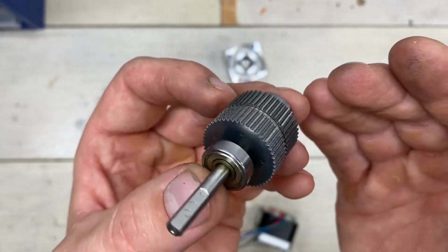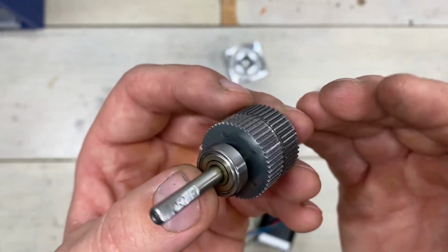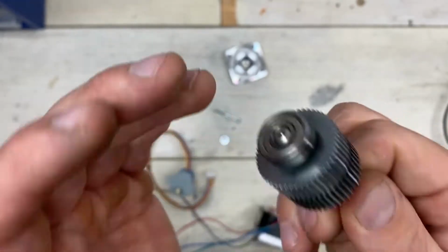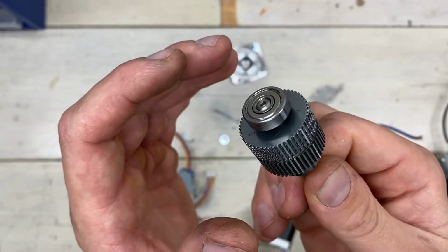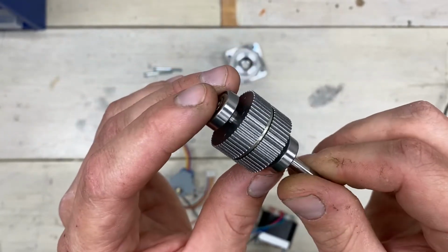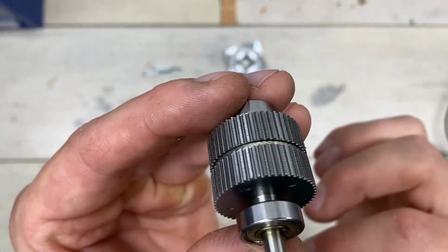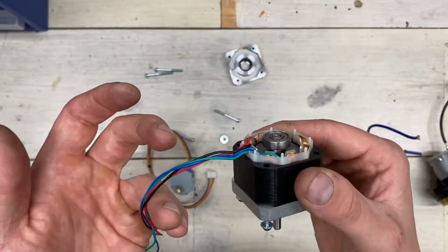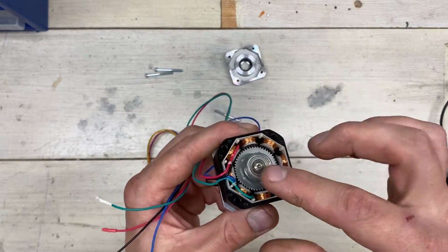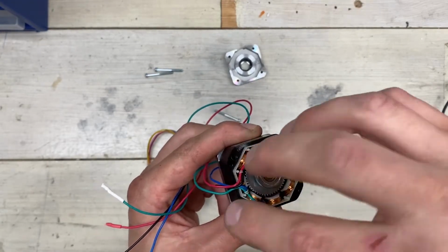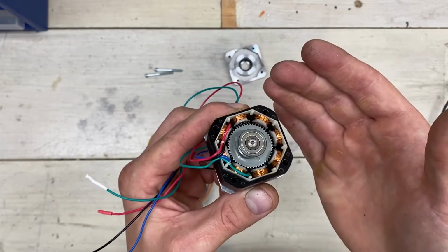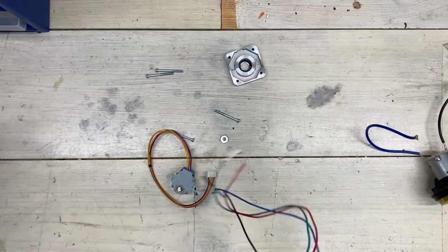Because stepper motors are generally designated by the amount of steps it takes to complete one full revolution. And the most common amount of steps are 200, or 1.8 degrees per step. And this is what makes the steps. So to achieve rotation in a stepper motor, we can't simply energize two wires and it will self-commutate and automatically move the magnetic field around the stator to turn it. We have to use something called a driver.